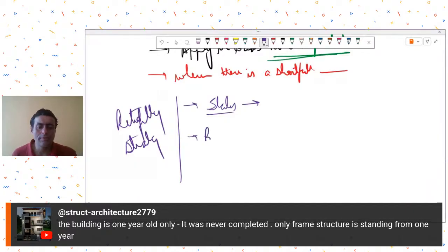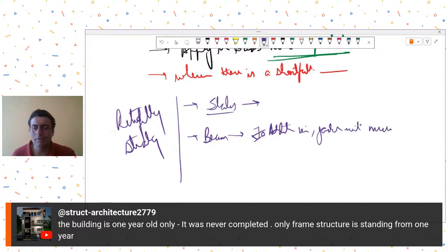If beams need retrofitting, then you may use the jacketing concept. So you may have to put additional reinforcement, and then follow it up by jacketing with micro concrete mixed with some polymer, etc. Or the other way could be to provide some steel structural frame.